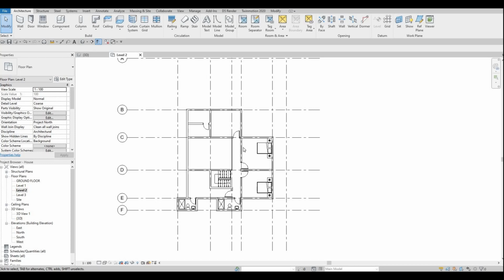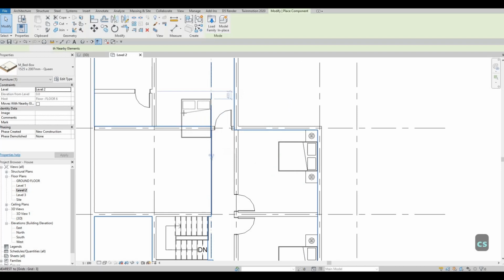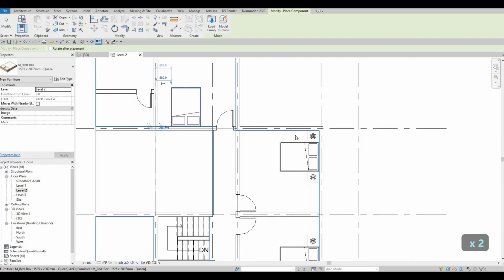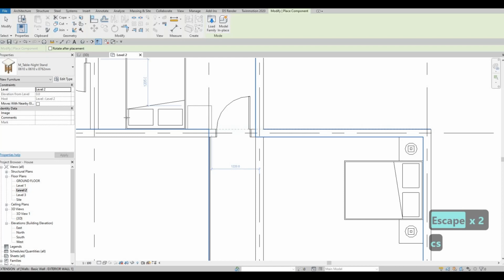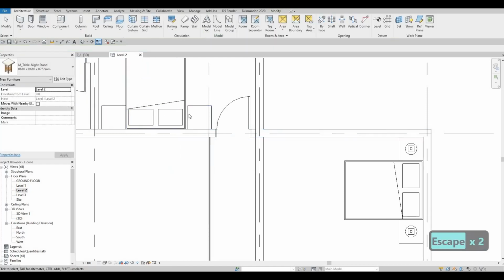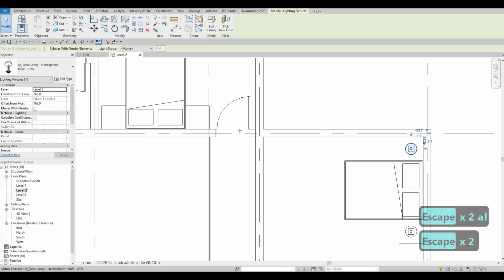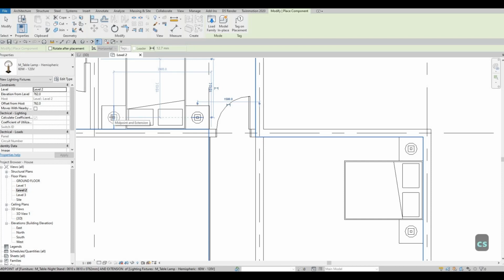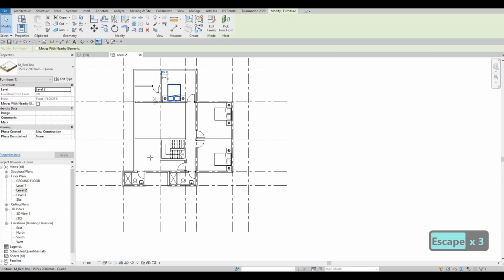So what I want to do is add in the beds first. So let's finish all the beds. So CS on that, spacebar to rotate, and then let's add it right here. And then the side table or the nightstand on the sides right here. And we want to make sure that this is aligned beside the bed so that everything looks nice. And then here CS on this and add it on the top. And then also let's add it on this side.